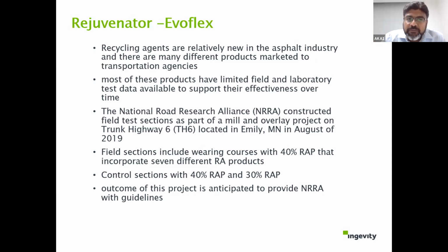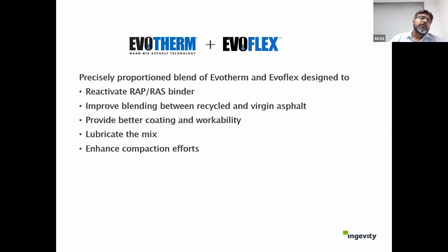And if you look at some of the projects we did in other places, they have gone up to 40% RAP with these kinds of rejuvenators. There are some guidelines that the National Road Research Alliance has given. You can also refer to the Asphalt Recycling and Reclaiming Association manual. That is one of the best for this kind of idea: how to use it and what precautions need to be taken.